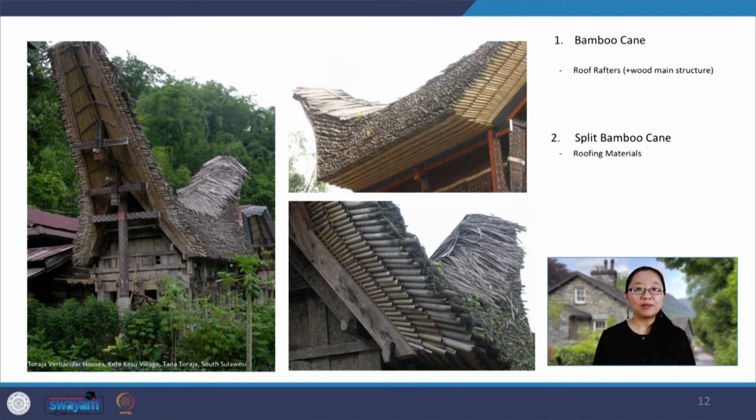The unique bamboo application is in the roof constructed with layered bamboo canes, cut or split in half, bound together with rattan, and assembled transversely in layers to keep the rainwater from entering the house. The layers are put over an underroof of bamboo poles, which are tied longitudinally to the rafters. Sadly, nowadays the bamboo roofs are increasingly replaced by zinc roof and nails.